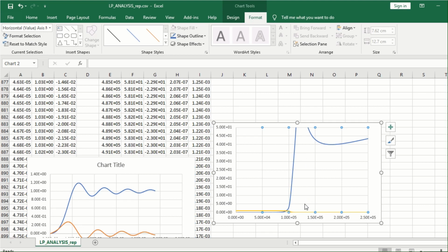So if you have some disturbance here in this region as an intermodulation result, something which must be suppressed before entering the transmission channel, then this kind of filter will be perfect for the application. It will suppress it even though it has some instability, some kind of changing in time. Now we will look to the passband.